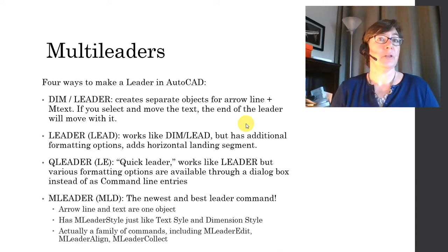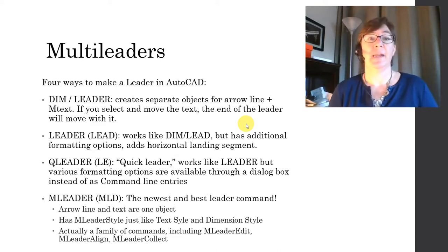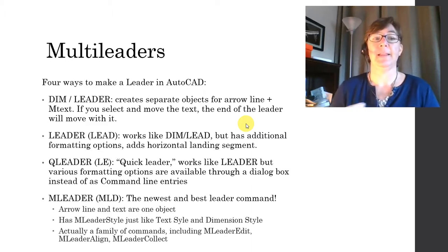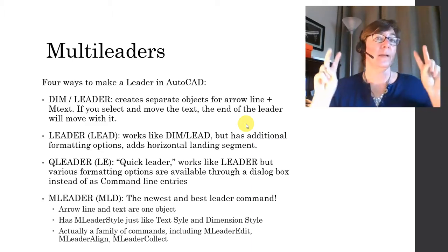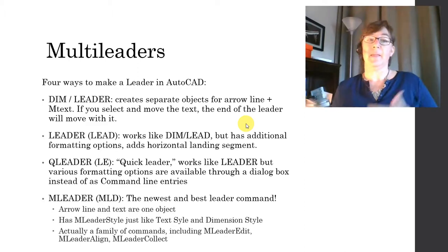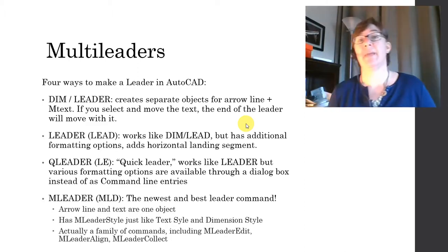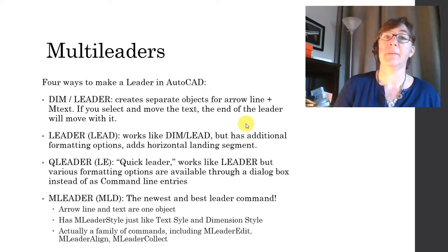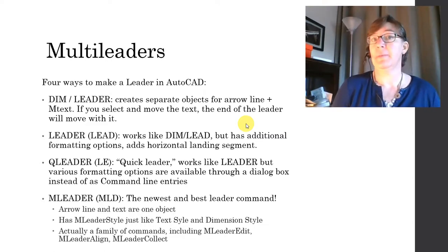The next option that AutoCAD created was QLeader. The shortcut is LE. It's a quick leader, so Q for quick. It works like the leader command, but all of those formatting options are available through a dialog box instead of command line entries, so a little bit more user-friendly.